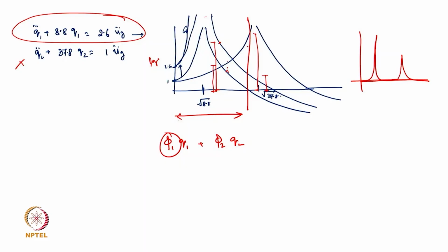Okay, so you will see that in most cases, after a few modes, your frequency will be very high, because time period will be reduced. So that will go out of the 0.5 range, and there will be no chance of resonance. That's why you are safe, no problem. Otherwise, we would have to do it for 100 modes, and maybe one or two days would be gone for designing. So that way the things are happening. I think you got an understanding of what is going on.